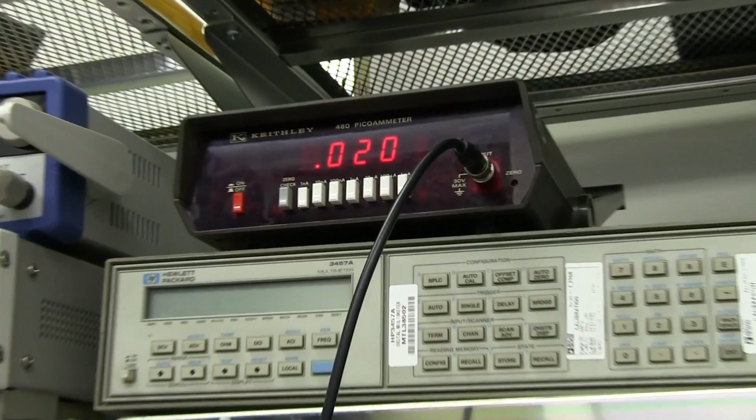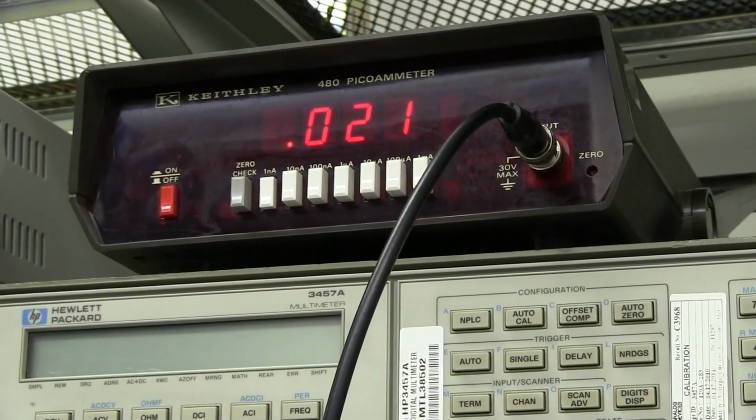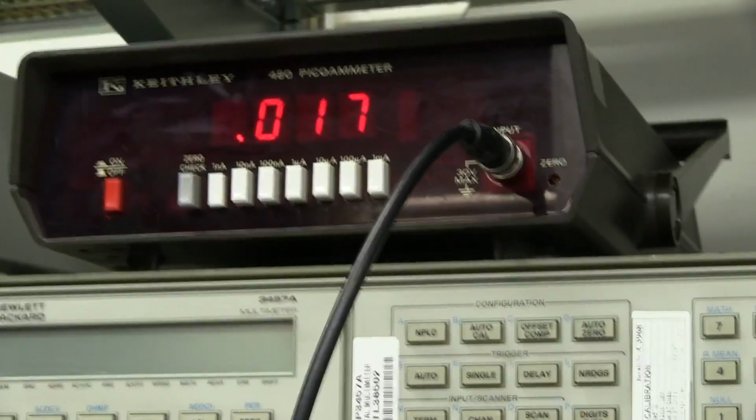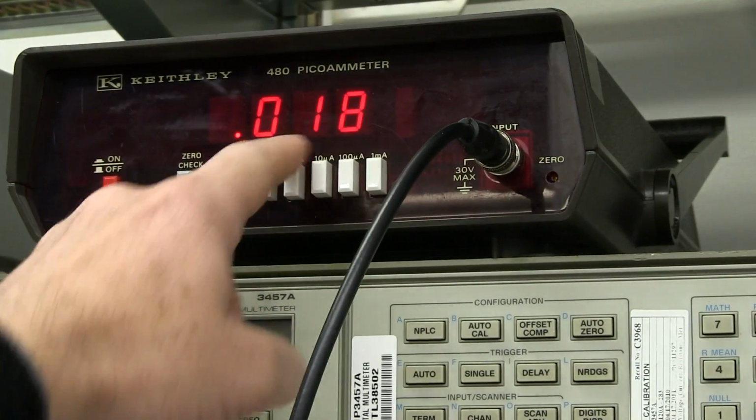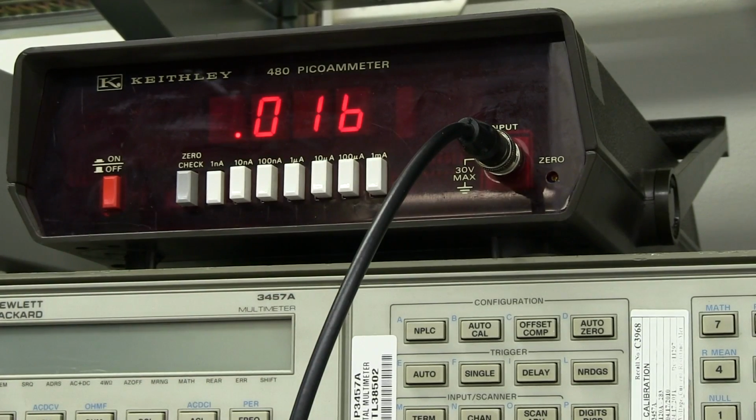Not particularly easy, but I've hooked up my Keithley pico ammeter. There it is, and at 5 volt supply rail, it's the 1 nanoamp range, so we're talking picoamps there. So 16, 20 odd picoamps into that non-inverting input. That's through that 100 ohm bias resistor, at 5 volts. And if I lower the voltage, that's 4.5. We'll probably see it change.